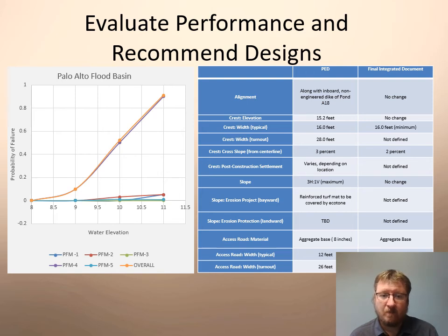And so on the left is an example of a geotechnical system response curve for a project, and how it relates the probability of this levee failing to the water elevation loading on the levee on the bottom. And so for this example, 5 different failure modes had potential to impact the levee, and then the overall failure mode in the orange is a combination of the other failure modes.